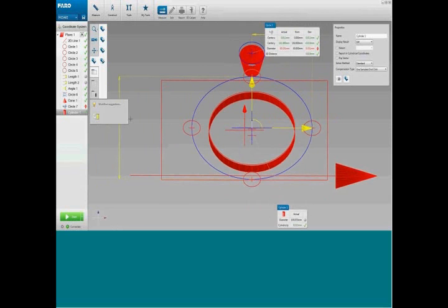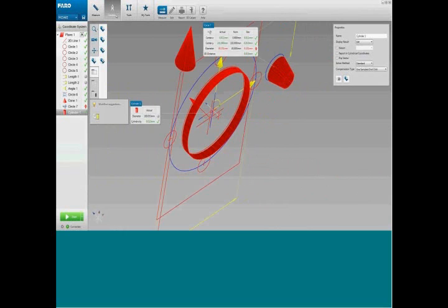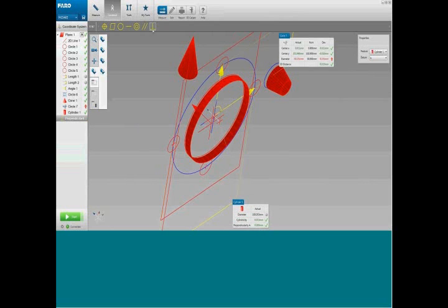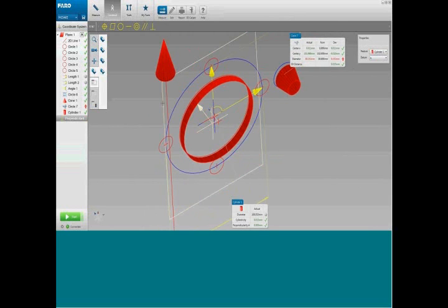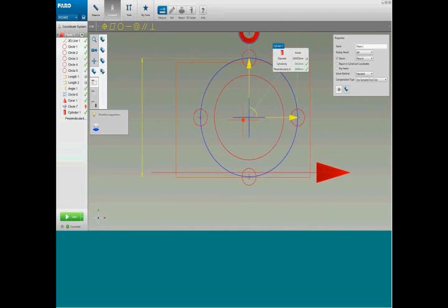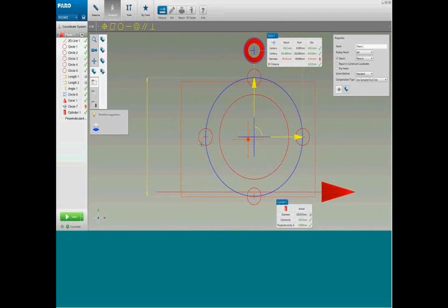Okay, so now to check the perpendicularity, I simply go to Construct, GD&T, choose the symbol for perpendicularity here. Then on the right-hand side, top right-hand corner here, we have the properties for the calculation. I choose a feature to be checked, in this case cylinder 1. I then choose a datum. And here on the label, you see we now have the result, 6 microns. Okay, so hopefully you can see there the workflow suggestions is very helpful and really simplifies the workflow.